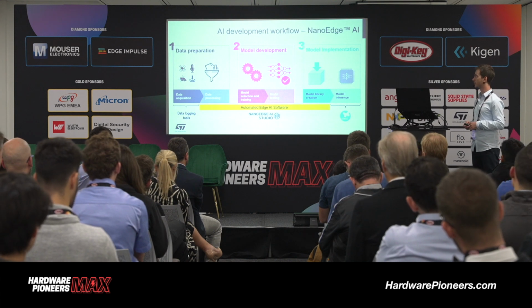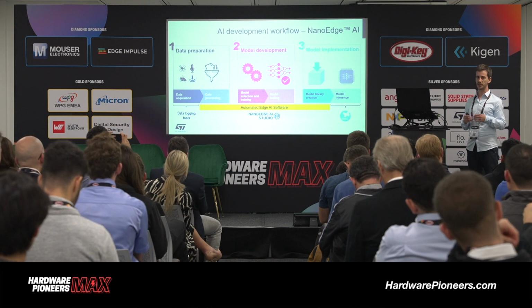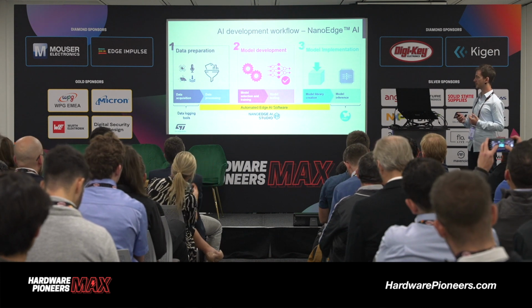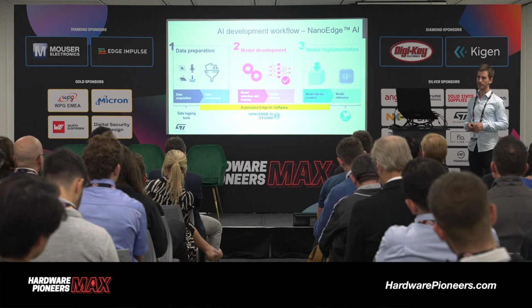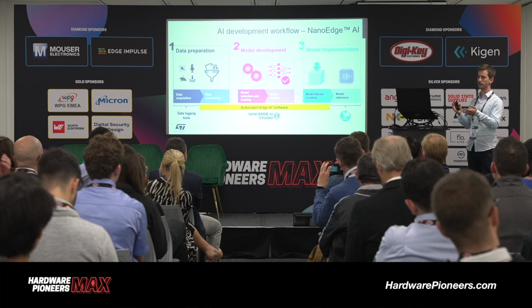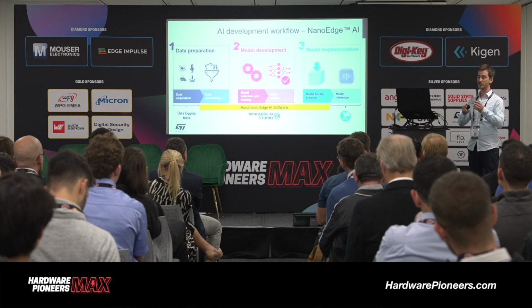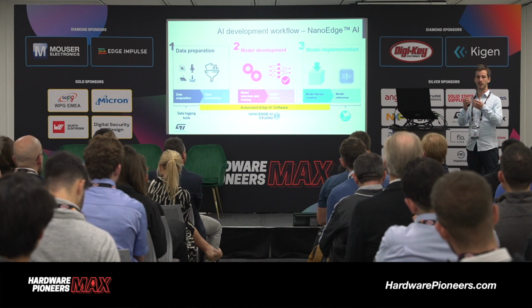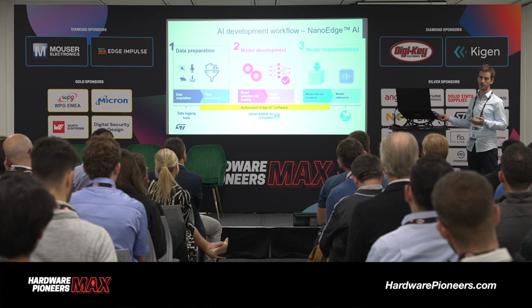And then you've got an alternative approach with NanoEdge AI, which is what I'm going to focus on today. Here, really, it's a tool that automates the whole process. For an embedded developer who doesn't necessarily have expertise in machine learning, it's a very nice way to do all these things, and it even includes now some data logging tools. So with NanoEdge, you can log some data, create your input data sets, then click a few buttons, and it will find for you the best model, which is step 2 here. We'll find not only the best model, but the best shape for this model and the best pre-processing for your signal. And then you can test that this library, this model actually solves your problems, and then deploy it on the field on any STM32 microcontroller.